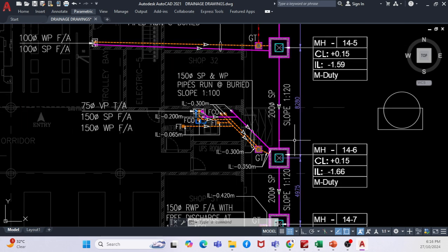So whatever we have seen, say for example from the second floor, below we have a riser pipe, then from the riser pipe it is going down to the ground floor. From the ground floor, all these pipes below the ground will be buried pipes. So that pipe will be connected straight away to the manhole.